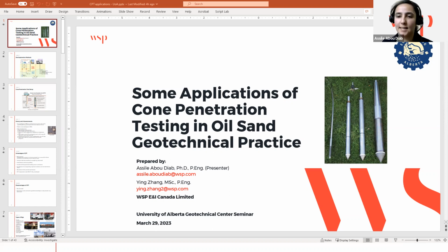So whenever we are designing a structure, if it is a strain softening material, we have to take into account the susceptibility to liquefaction. So yes, strain softening soil, we have to assume that they are prone to liquefaction and run our analysis based on this assumption.